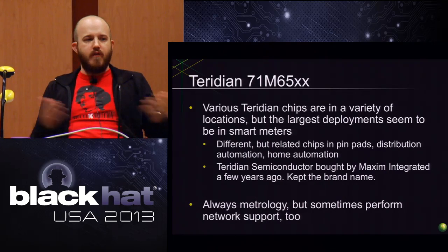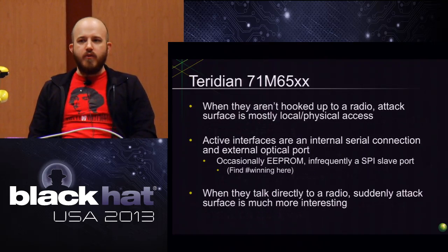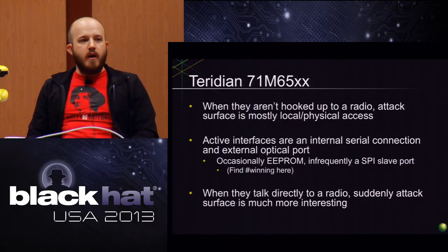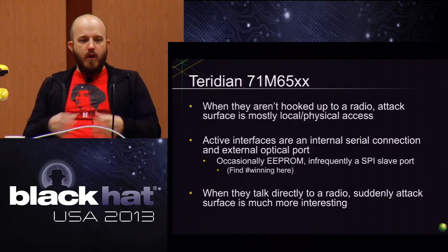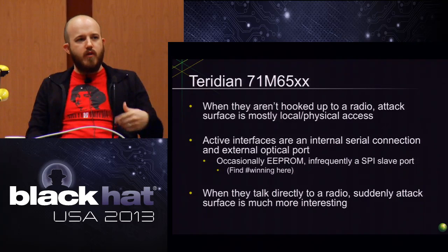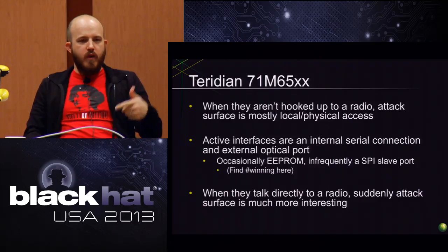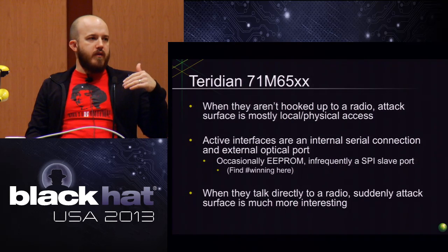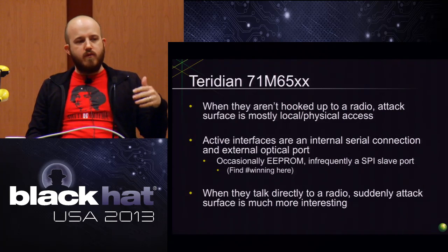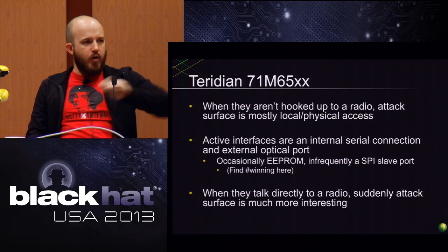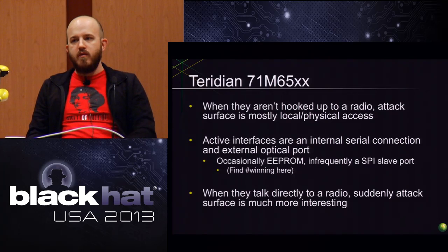And then how it talks to everything else, that gets different. There are standard interfaces into this chip, but serial is the most common one, and then that can talk to whatever they want it to talk to. It could talk to another board that is an entire computer in its own right, doing whatever it's doing, and just ferrying commands back and forth. Or it could be doing straight pass-through, and the Teridian chip itself could be speaking something like ANSI C12.22, the one for network communications, and then you've got actual packets terminating inside the Teridian chip itself.